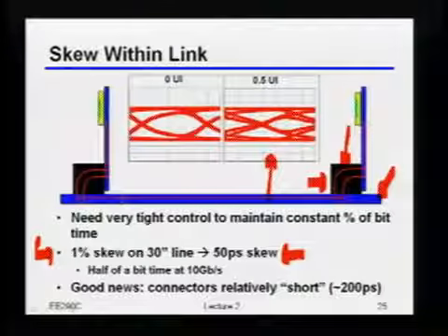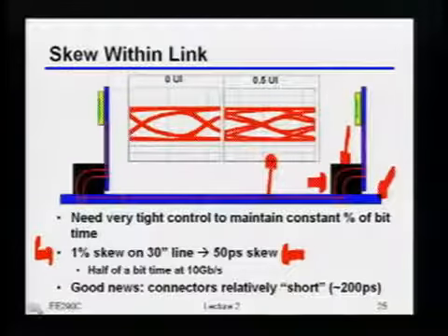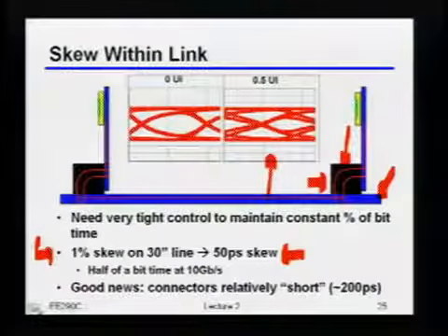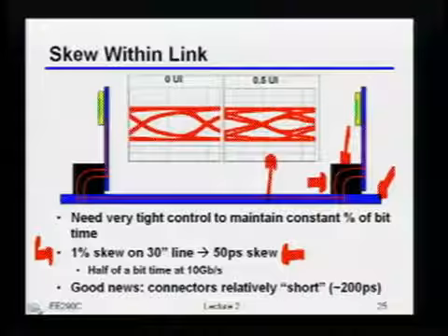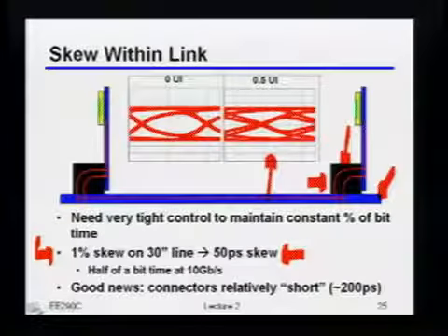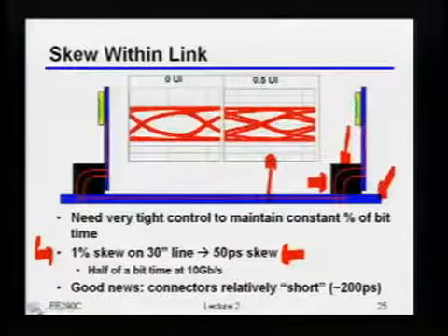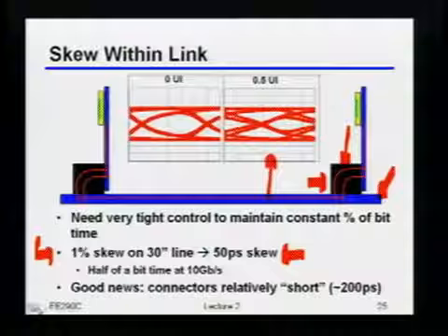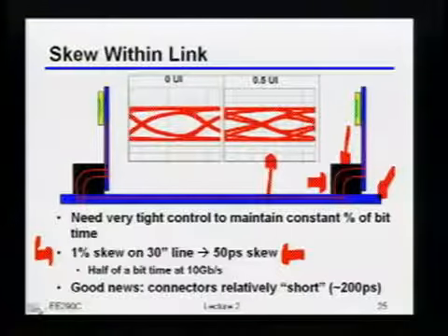Now, that's not to say that if I looked at the S21s of those different channels, they could indeed actually vary quite a bit over the manufacturing range, which, as we'll talk a lot more later, means that, even if you knew exactly which PCB you were going to be working on, there's still going to be some range of adaptability you'd need just to handle the variations in the PCB itself. It's a great question.